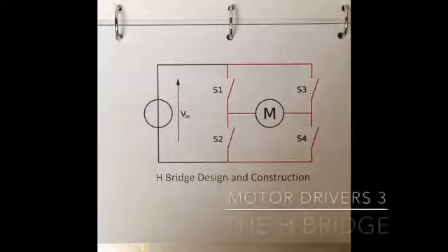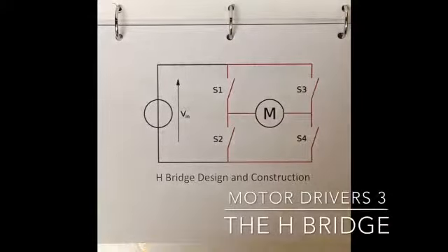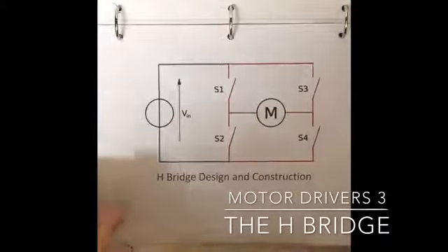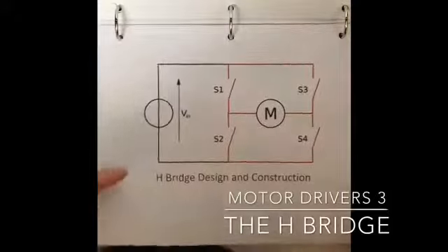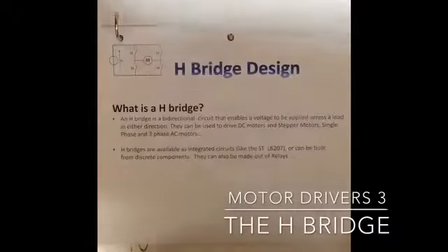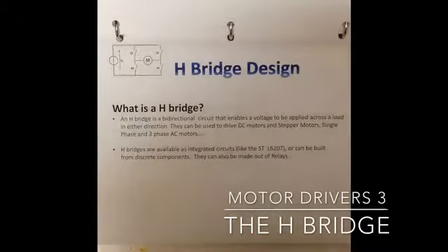Alright, let's go to part 3. Start looking at H-bridge design. This is just sort of an overview of the way I look at the world anyways. It's pretty straightforward. An H-bridge is a bidirectional circuit that enables voltage to be applied across a load in either direction. So you can use it for a DC motor or stepper motor or single phase even or three phase motors.